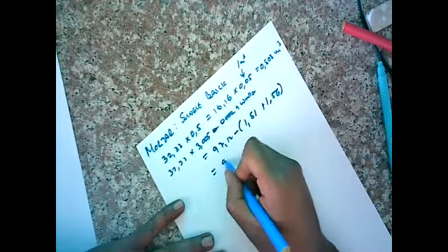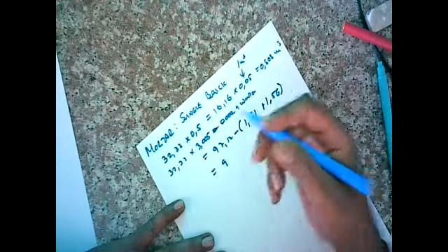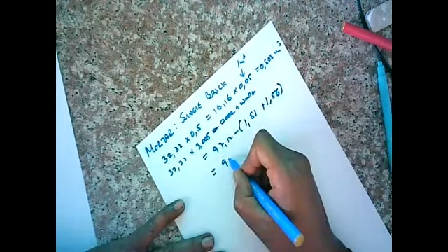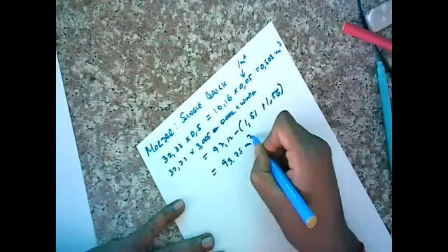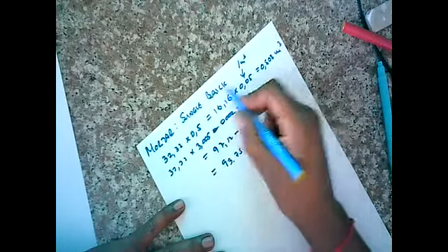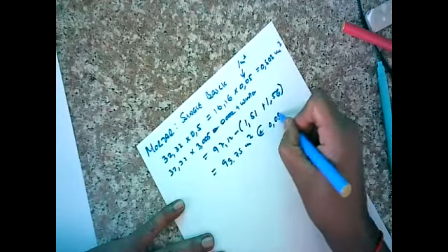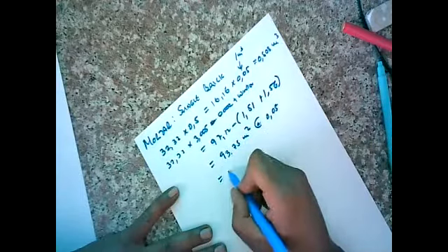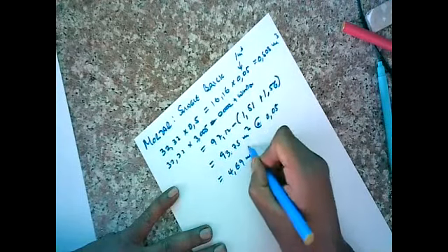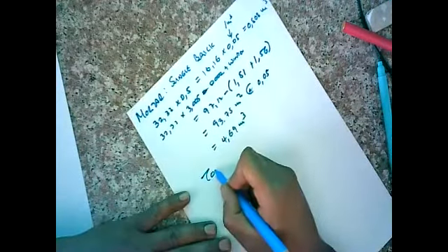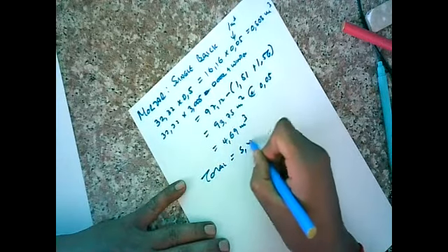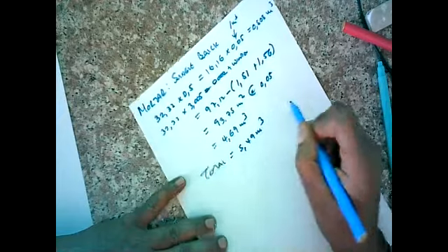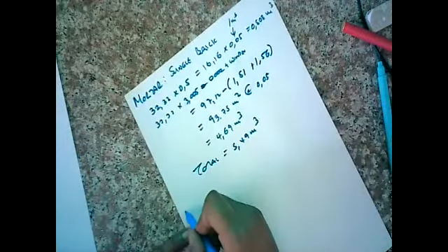And I got an area of 90. Remember, I did area of brickwork here to find mortar. So that's what I'm finding. 93.75 meters squared. And this is single brick right there, and 0.05. And we get a value of 4.69 meter cube. And our total for this is now 5.49 meter cube. All right, so mortar still.